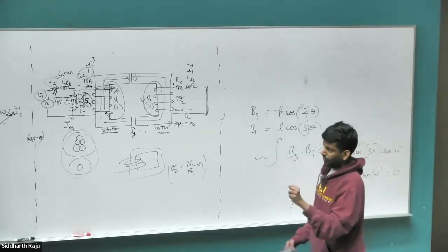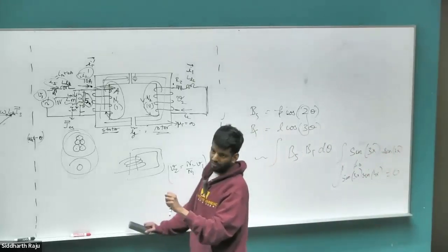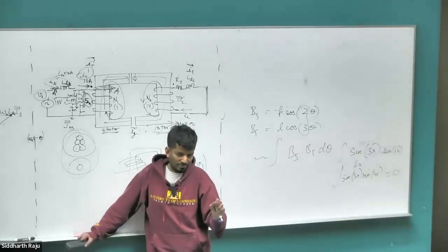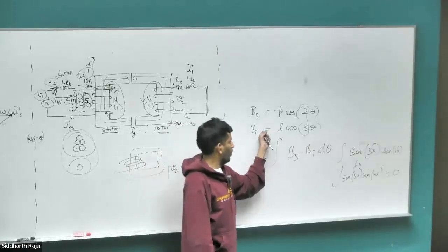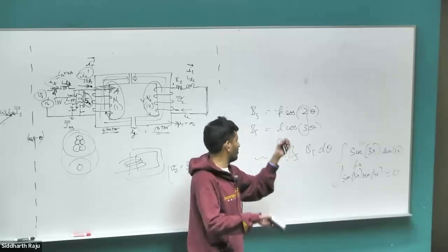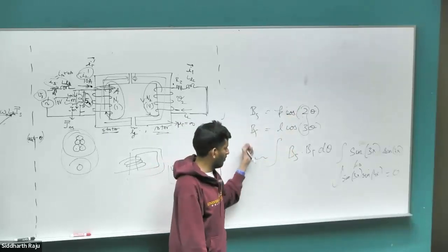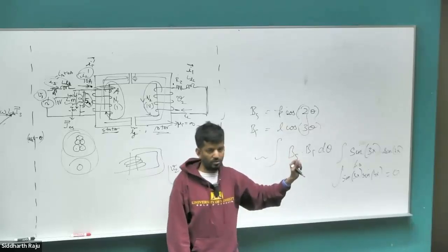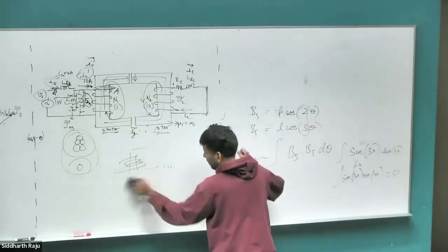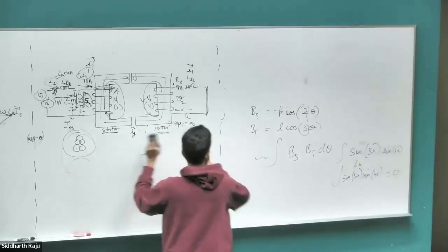By the same logic, we know that induction motors do operate and produce a torque. So just based on that, the rotor poles, however they develop, must be exactly the same as the stator poles if torque is going to be produced in the system. Otherwise, from our Fourier analysis, we know that no torque will be produced at all. So let's visualize and see what's going on.